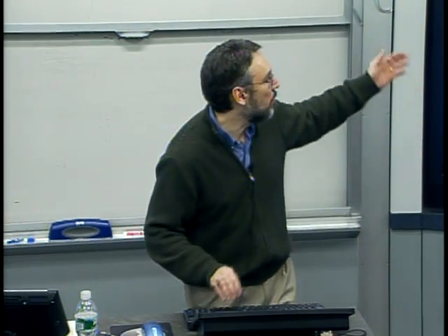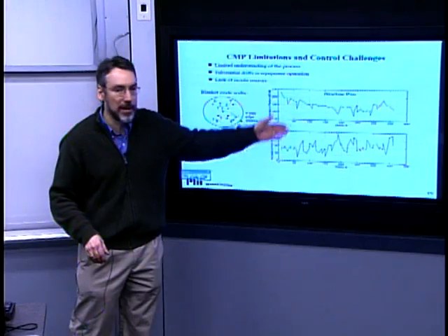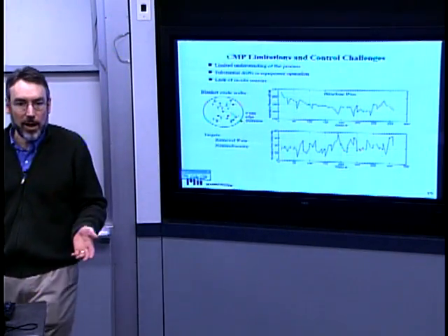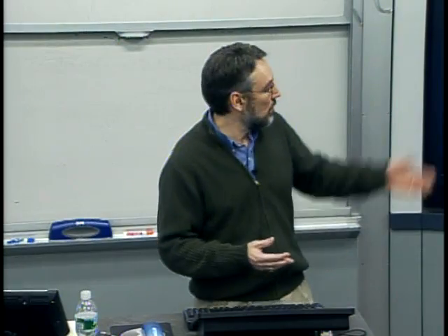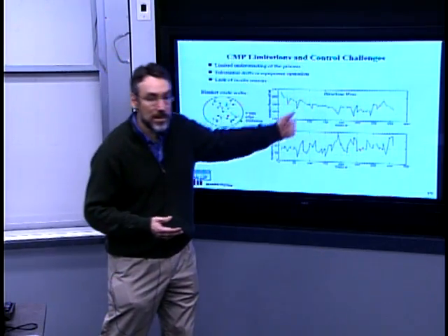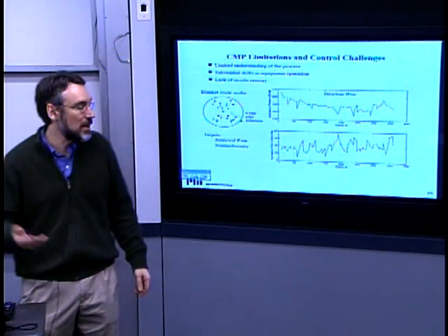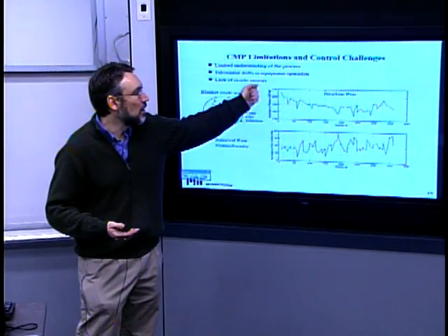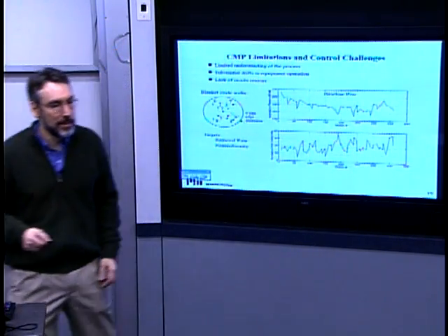The pad is not quite as uniform as well. So this is the kind of temporal wafer-to-wafer variation that you don't want, and we would like to understand it. If there's a systematic trend, then maybe there are control approaches that can be used to compensate or correct for that. Yeah? This polishing seems to be a bad idea to me.